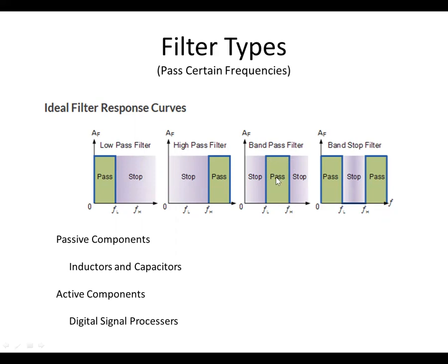This is the kind of filter, and it would have to be adjustable, if you were using it to tune a receiver to listen to different frequencies. As you move the bandpass window, you let through a different range of frequencies than you had before, and that's how you tune a receiving antenna to just let in the frequencies you want.